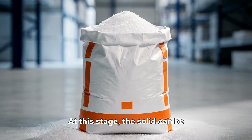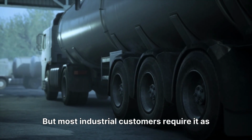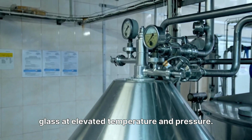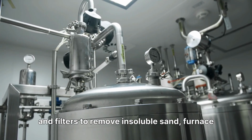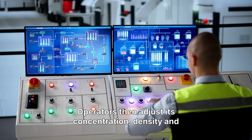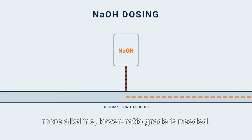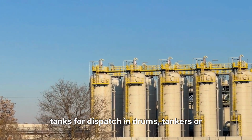At this stage, the solid can be crushed and sold as granular sodium silicate, but most industrial customers require it as a liquid. The fragments therefore enter a pressure dissolver, where hot water and steam dissolve the glass at elevated temperature and pressure. The resulting solution passes through settling equipment and filters to remove insoluble sand, furnace debris, and other contaminants. Operators then adjust its concentration, density, and silica-to-soda ratio. Sodium hydroxide may be added when a more alkaline, lower ratio grade is needed. Finally, the liquid is transferred to storage tanks for dispatch in drums, tankers, or rail cars.